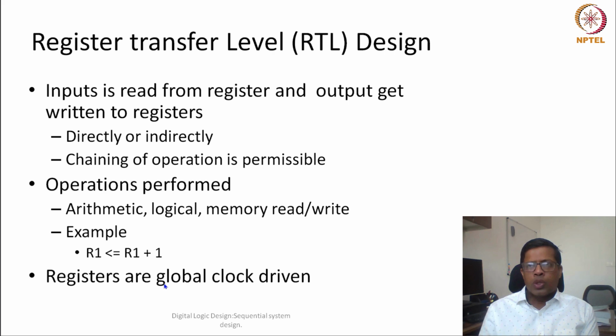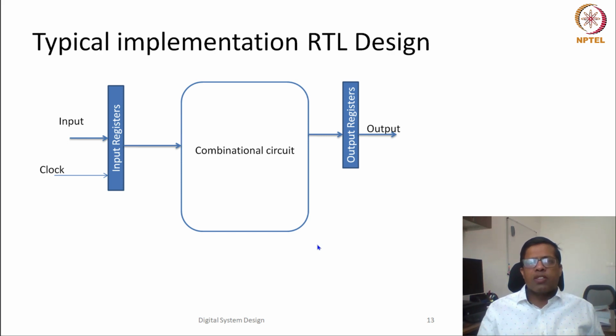They are assumed to be made up of flip-flops, which means they are always edge triggered registers. So only after an active edge comes will the results be applicable on the output registers, but before that active edge, the operations can be performed. We have seen this diagram multiple times.